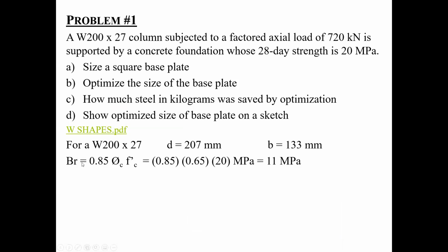Now, guys, the reason why I say factored resistance, I want you to keep this in mind. Factored resistance is simply because I'm always using some kind of reduction factor, and I'm not using the full 30 MPa. That's what we mean by factored resistance. For example, factored resistance in steel, we use a phi, you understand? That's what I mean by factored resistance.